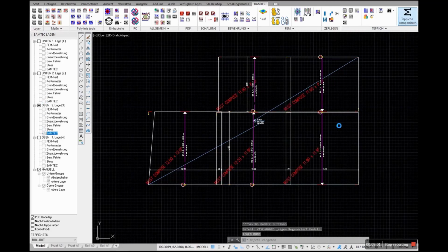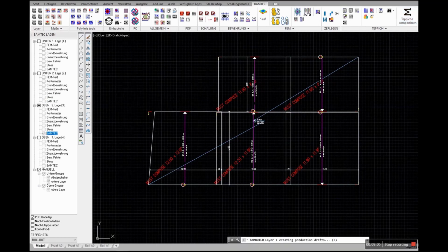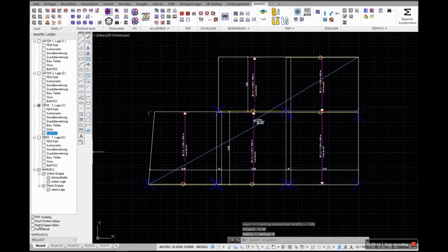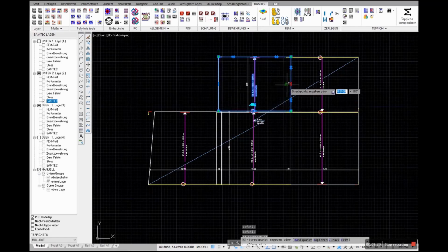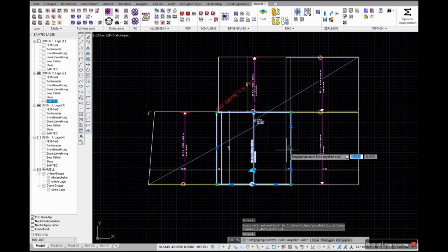It could be done manually if you need it in the other layer as well, but normally it's enough to copy the basic reinforcement or the geometries, because the basic reinforcement is a different one anyway. This is all rather convenient. The carpet geometry copied, the basic reinforcement copied. Then you can also change the basic reinforcement with 2 simple clicks, but you can retain the carpets as they have already been put in.